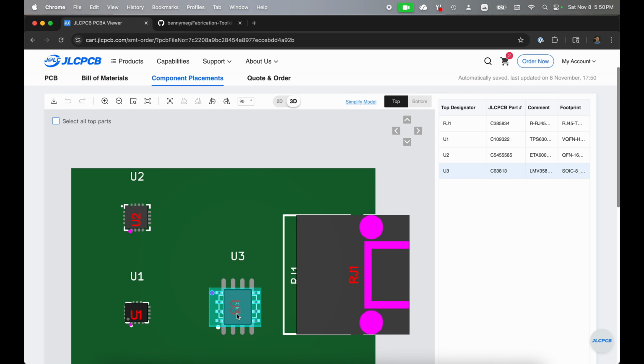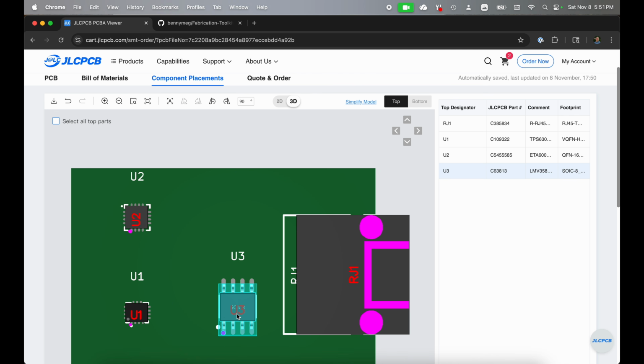So now we're going to deal with our op amp, and if we go in here and we hit space, we notice we just rotate it 90 degrees and it's now in the right position. Now, the fact that this is counterclockwise, you might think that was negative 90 degrees, but no, because it's the default direction that this tool wants to operate in. That counts as 90 degrees. Right? And if we look at this one up here, you can see 1, 2, 3. I had to do it 3 times, so that's 270 degrees or negative 90 degrees. So for U3, we have to rotate it 90 degrees. For U2, we have to rotate it negative 90 degrees. And for U1, we're just fine.